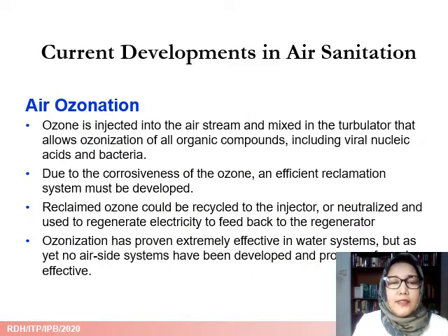Another technology under development is air ozonation. Ozone is injected into the airstream and mixed in the turbulator that allows ozonization of all organic compounds, including viral nucleic acids and bacteria. Due to the corrosiveness of the ozone, though, an efficient reclamation system must be developed. Reclaimed ozone could be recycled to the injector or neutralized and used to regenerate electricity to feed back to the regenerator.